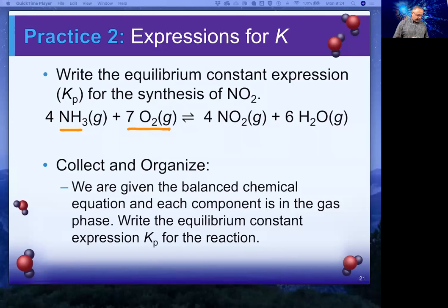And so the transformation of NO2 into nitrates is not that complicated. But this reaction here is the one that is challenging. So there's a precious metal, platinum, that is used to do that. There's such a flow of gases put through that mesh, and the mesh is very thin, and yet it has to convert about 90% or 95% of all the ammonia and oxygen into nitrogen dioxide and water.